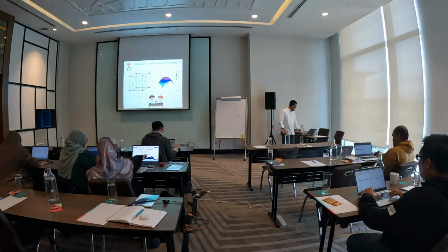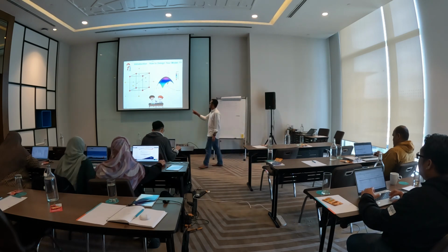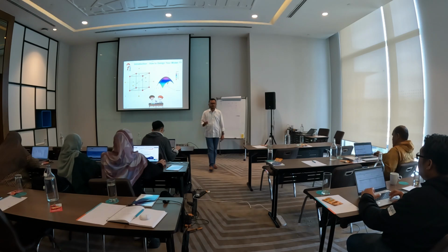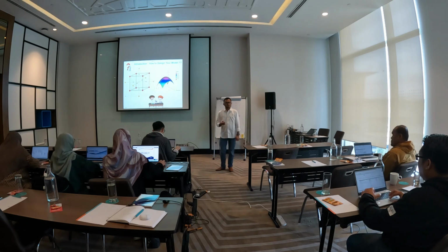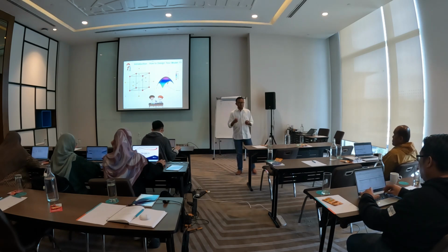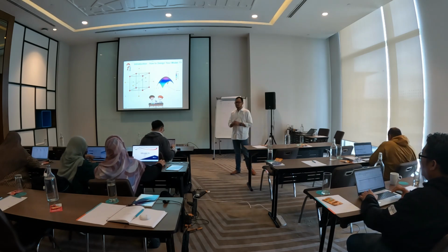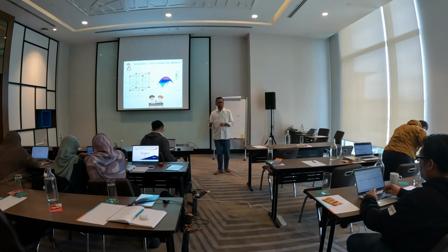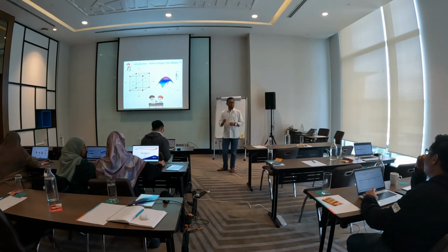Okay, next. How to design your model. Normally, in this case, we will have some parameters like pressure, or temperature, or flow rate, or all those things. So we don't know where the optimum condition is. So in DOE, the first is the screening method, where we can have two levels, maybe the minimum point and the maximum point. At that time, we run one case, and then we can gauge where the optimum point is. After screening, we can run another experiment to get the very optimum point for this experiment. Okay.